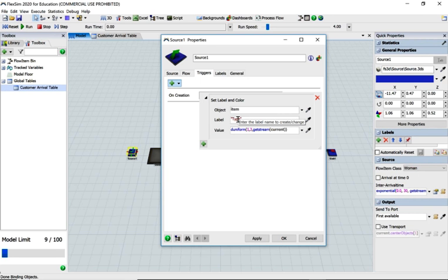And selecting the item type and color, we're going to use something called empirical. Brackets, and there it's found our table now. It's in quotation marks. There we go. So it's not going to create them in the 20% of item type 1, etc. in that order. It's going to mix them up, but use the percentages coming from that table. So let's apply it and say OK.